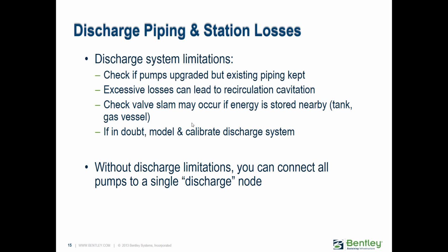You can also have a check valve slam occur if you have a check valve built in there, especially if there's a nearby storage tank. Like if you have a hydropneumatic tank just downstream, there's a very good chance that that check valve is going to slam when that pump shuts down. So that's definitely a concern as far as the discharge system. If you're ever in doubt, model it in the program and calibrate the discharge system to measurements that you've taken in the field.